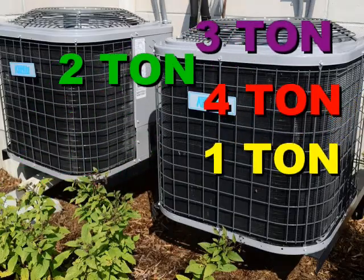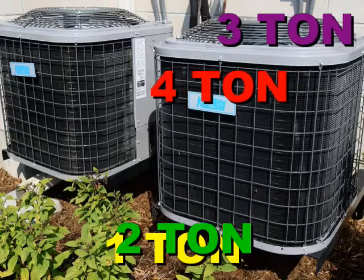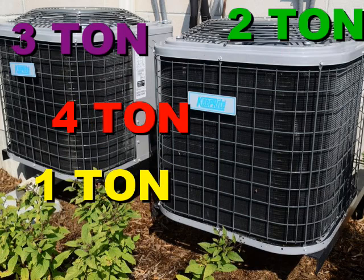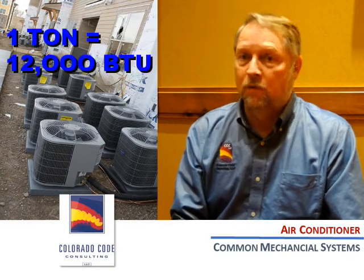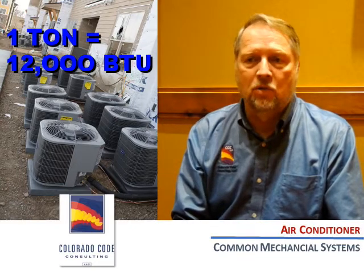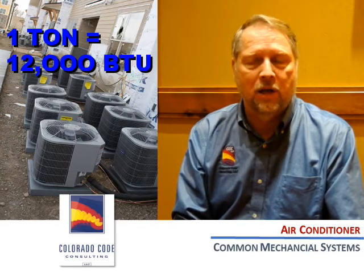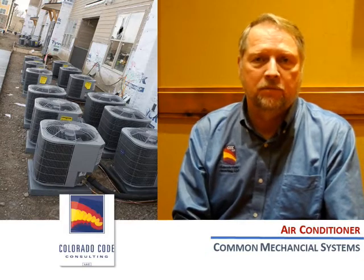Generally, most times our AC system is referred to in tons. Okay? Well, what's a ton? Well, it takes 12,000 BTUs in 1 hour to melt a ton of ice. That's where the ton comes from. So a ton equals 12,000 BTU. The higher tonnage results from higher energy usage. This is part of the required equipment sizing process, the whole Manual S piece. So we don't have a 5-ton air conditioner when we only need a 2-ton.